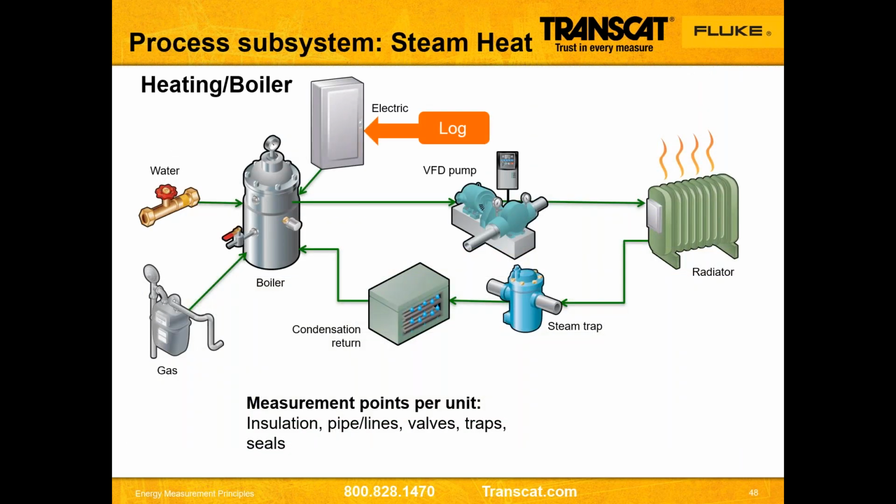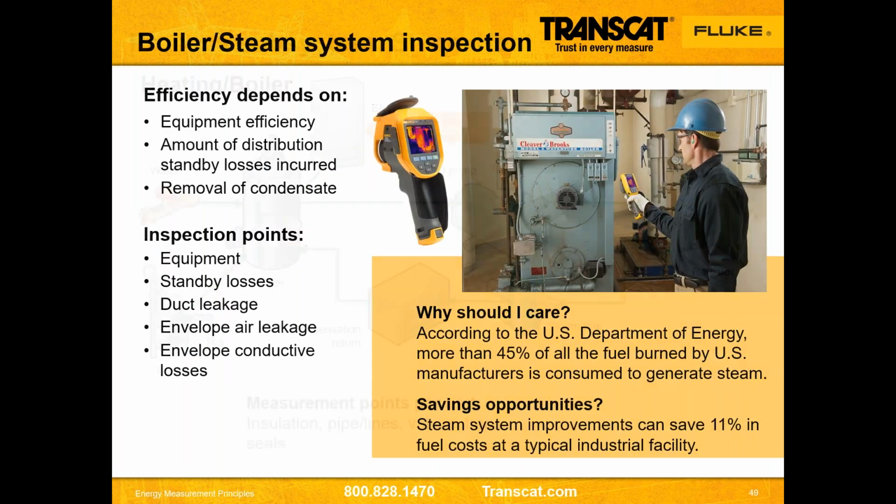Same thing on the heating. So steam loss, right? We are going to fire a boiler up using either oil or natural gas or some other kind of fuel to create process steam. We're going to regulate that. We're going to run that through our system with a pump. We're going to put it out through steam traps to regulate, to control that steam flow as it goes through the building or the plant. We need to make sure all is working properly.